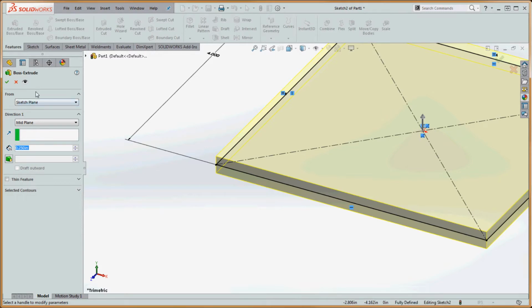And we have a couple different choices up here. We're going to cover this with a little bit more detail later once you get some SolidWorks under your belt. But we're sketching from the top sketch plane, but we can sketch with other choices in here too. From a different surface or a plane, from a vertex. If you already have geometry that's in here, you want to put your sketch geometry in one place, but be able to put your extrusion in another place. You could do that too by going to a different surface or a vertex.